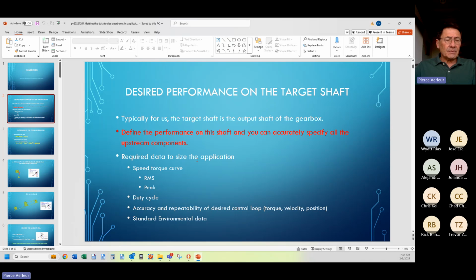In other words, if you're on a dial plate and you need to turn that thing to 0 degrees, straight up on the clock face, accuracy is how accurately you get to 0 degrees. If your accuracy is plus or minus 1/10 of a degree, then you're going to vary in position around 0 degrees. Repeatability is how often you get to the inaccurate position defined by accuracy.